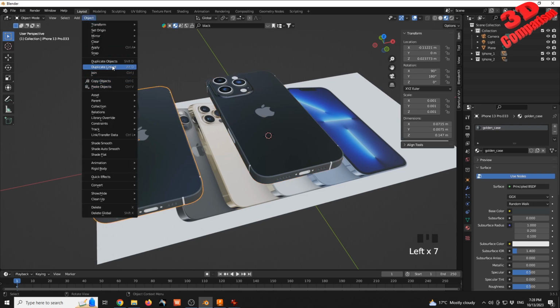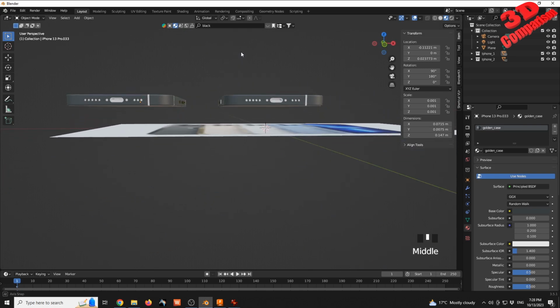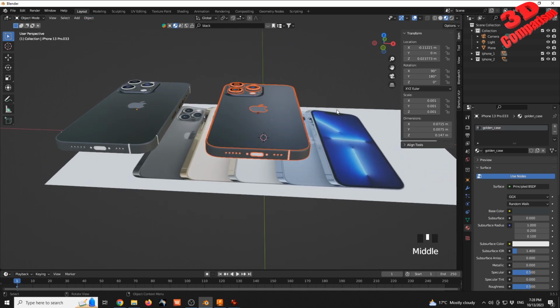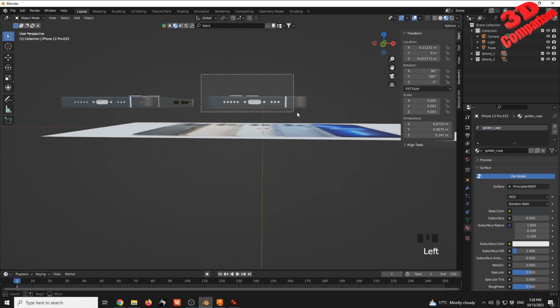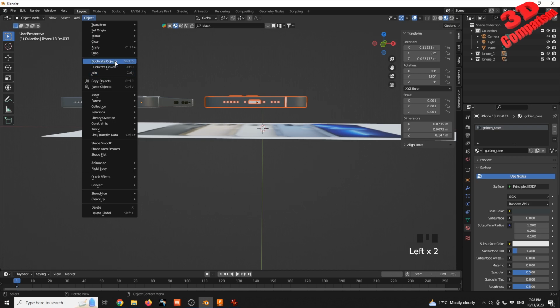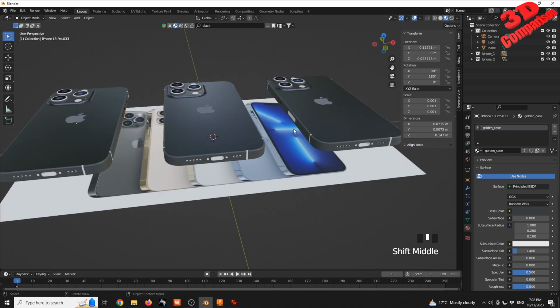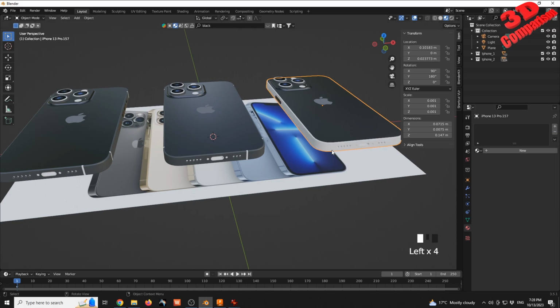Let me see exactly. Then we should have made a duplicate using the duplicate objects like this, and now grab X, so with everything over here selected, duplicate objects, grab on X, move it over there, and if I delete this material, only this one will be deleted.